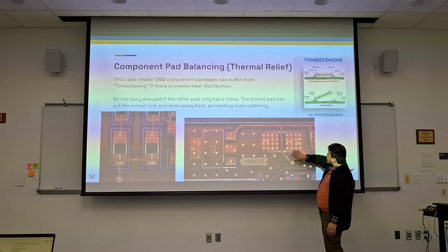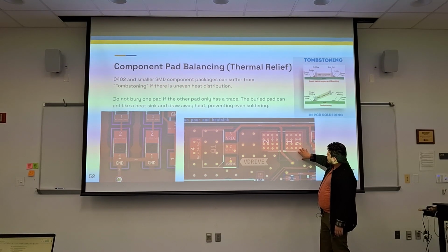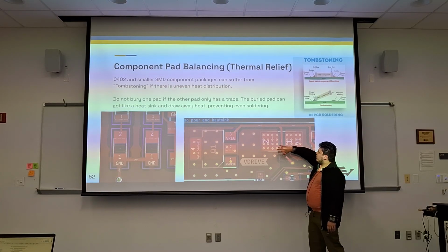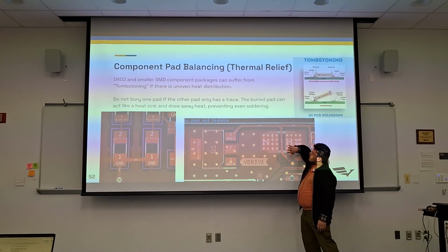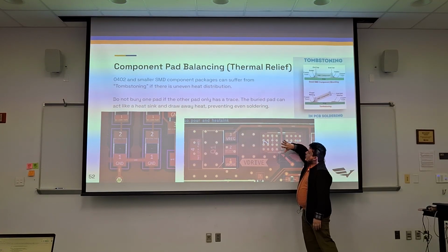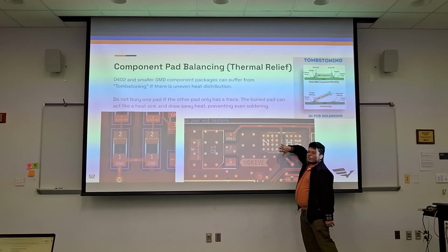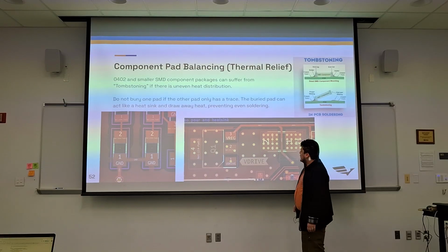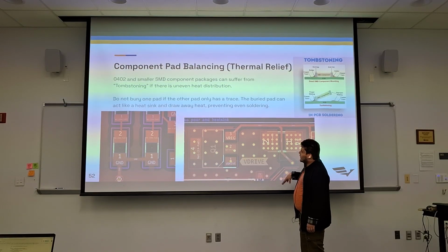So in this case, there's a risk that over here, since there's not as much heat being pulled away, our component actually lifts up from this side because we don't have a lot of heat heating up the solder joint. So we get a cold solder joint and our thing is lifted, and that is no good. And so that's what happens when you bury everything.